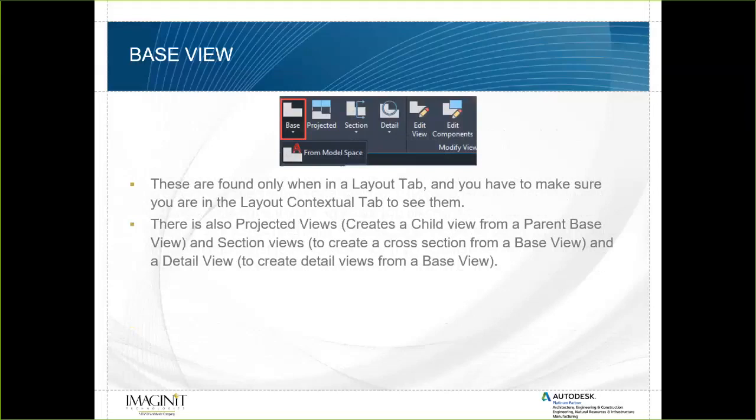So these are found only in the Layout tab, so make sure that you are in the Layout Contextual tab to see them. You will see that there is projected views here, which creates a child view from a parent base view, section views to create cross sections from a base view, and a detail view to create detailed views from a base view.